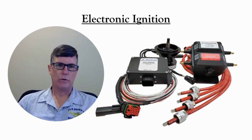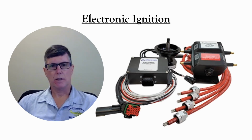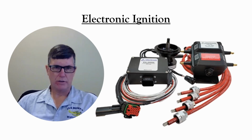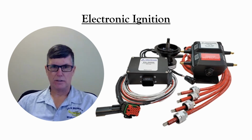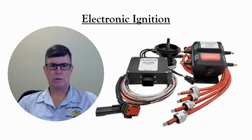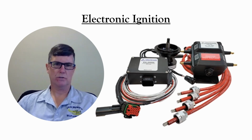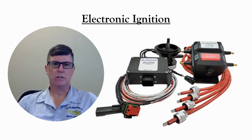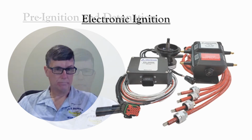Some aircraft have electronic ignition systems in place of one or both magneto-based systems. Electronic ignition systems, which are commonplace in modern cars, have a number of advantages over a magneto-based system. Electronic ignition produces a stronger spark than a magneto, and the timing of the spark can be adjusted based on engine speed so that combustion starts earlier when the engine's running fast. One disadvantage of electronic ignition is that it requires a separate source of electric power, like a battery.